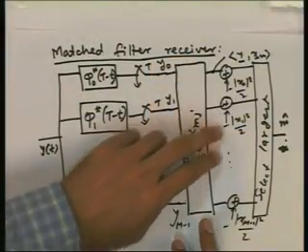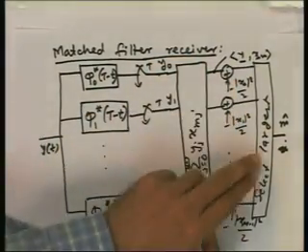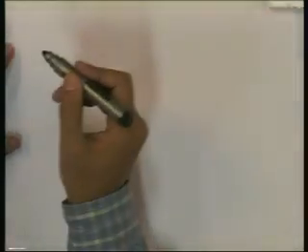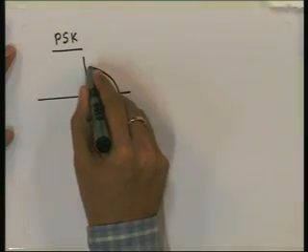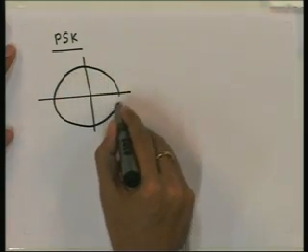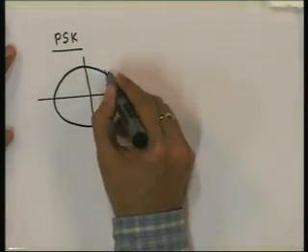Now, for PSK again the dimension is 2. So, we can use the same matched filter structure with 2 basis signals, and then here instead of doing this correlation and then finding this, for PSK signal particularly we can do it in a slightly different and easier way. So, for PSK we have this transmitted signal set. Suppose 8 PSK.